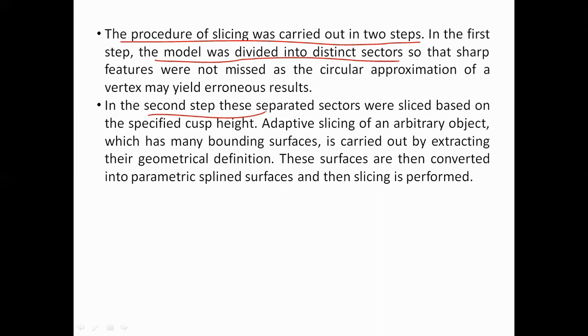The advantage of this process was that the slicing you obtained was now based on a mathematical number, and that mathematical number could be easily optimized. The slice thickness for each layer was now a specific number rather than a range. With the help of Kulkarni and Datta's work, we could easily get the specific number for the layer thickness, or the specific height of the layer, that can be used in order to create a part for every section.